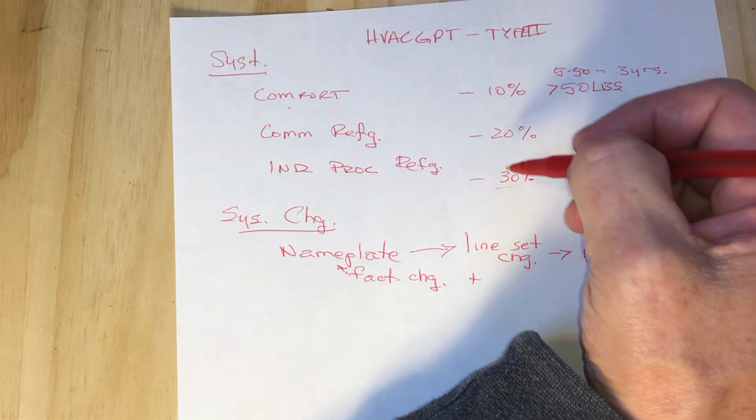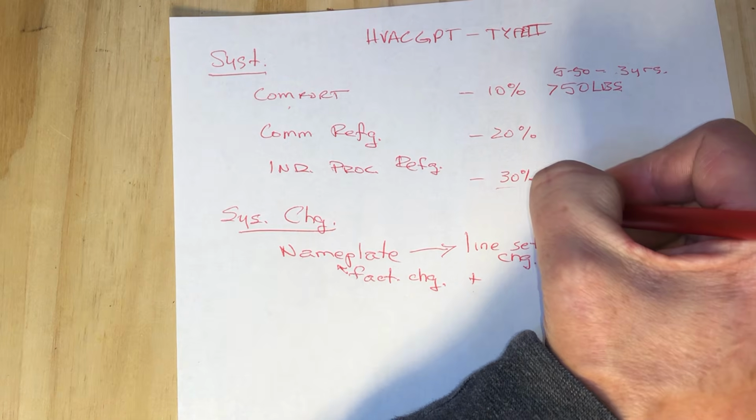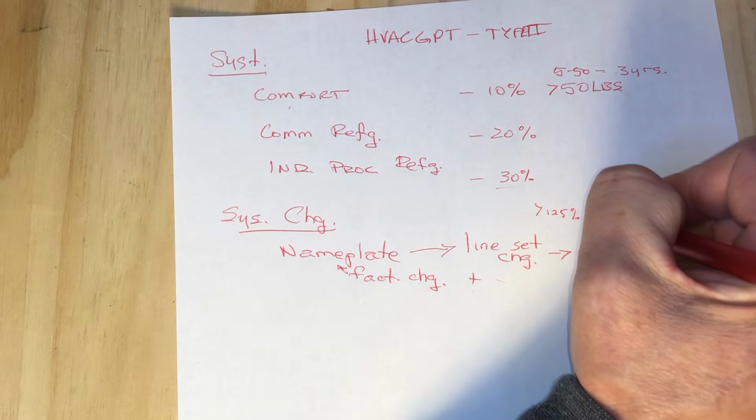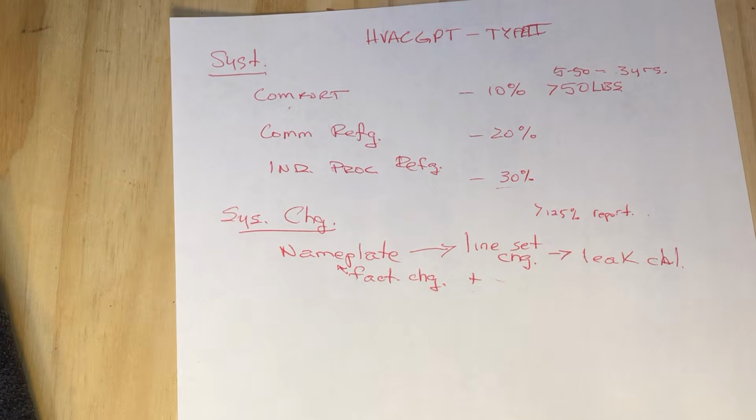So, one of them, if you are exceeding 125% of the total charge, then you've got to report that to the EPA, okay? And that's going to be one of the new requirements there that they're looking for. The other thing is that if you have more than 200 pounds of refrigerant, then you're going to have